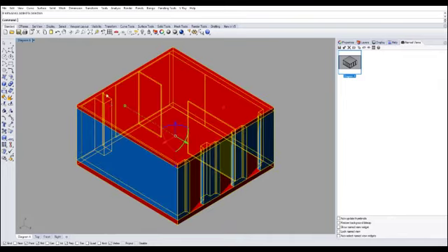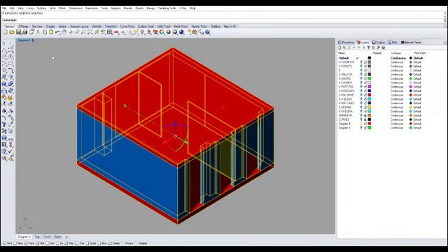Just like we did with diagram A, we don't want to ruin this particular setup of the diagram series B. So let's duplicate this and then make a diagram C layer and start our new exploded axonometric render from there. So let's go to the layers, select everything, same thing as we did before, control C, copy and paste.